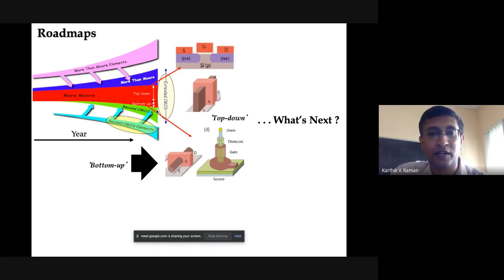That's what Intel and GlobalFoundries are aiming for right now. What that basically means is we're talking about a distance between the source and drain electrodes of the order of 5 nanometers. And that's a huge challenge in terms of controlling the gate, controlling the channel just below the gate. There have been improvements, like the concept of a wraparound gate, where you put a gate on 3 sides and it gives you better control of your channel between the source and drain.